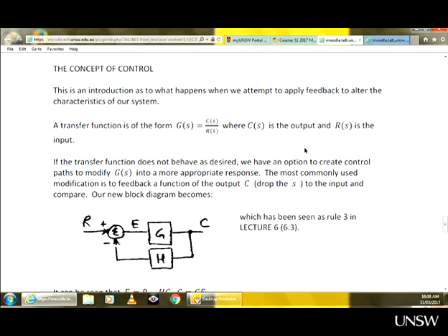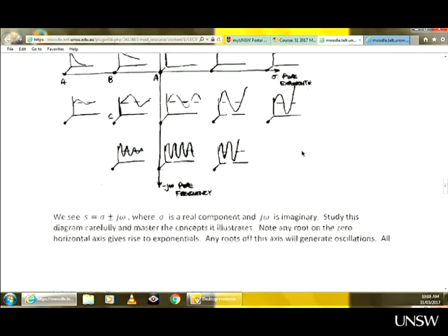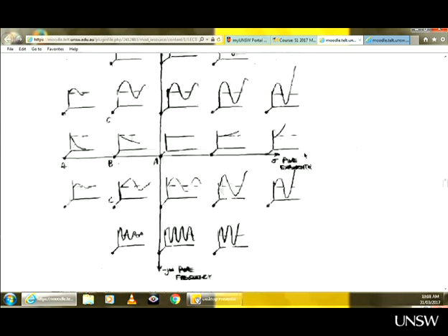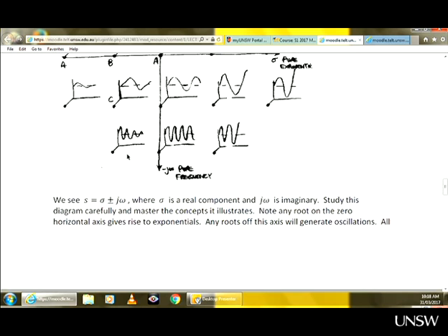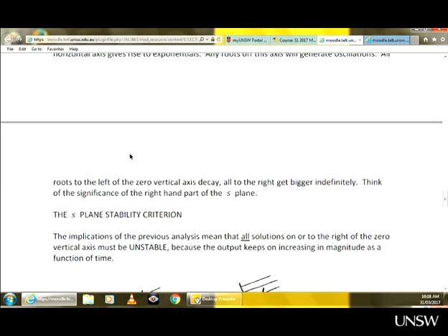We described the relationship between the placement of the roots in the S-plane and the behavior of the system. So just to confirm what we had, an overdamped system. We had 2 roots, something like A and B. So 2 real and different roots, both negative. That makes a system an overdamped system. So therefore, we have exponential behavior, but these are impulse responses, this one and this one. A step response will still be exponential, but the steady state value will not be 0.